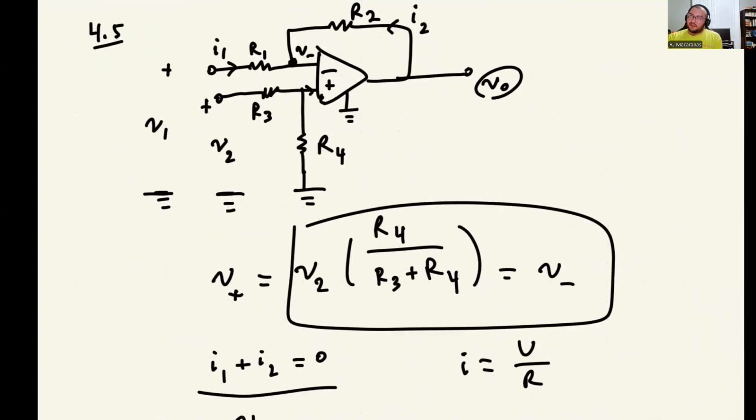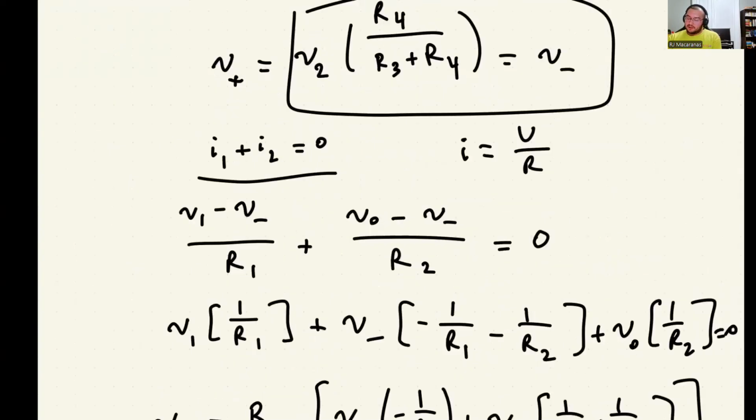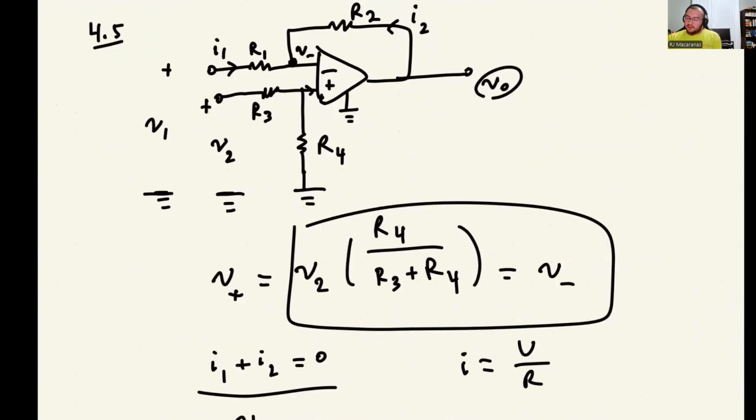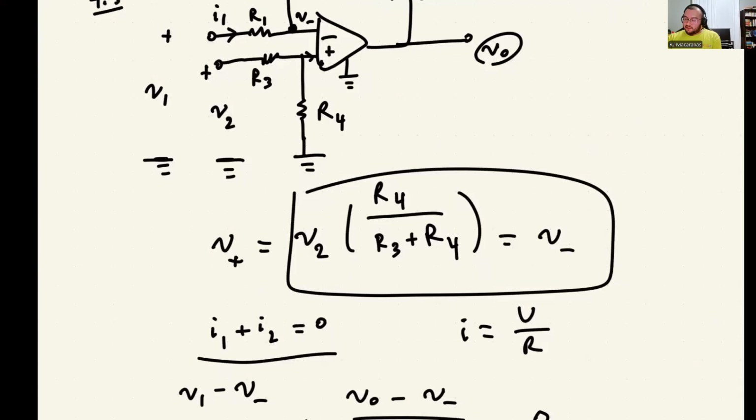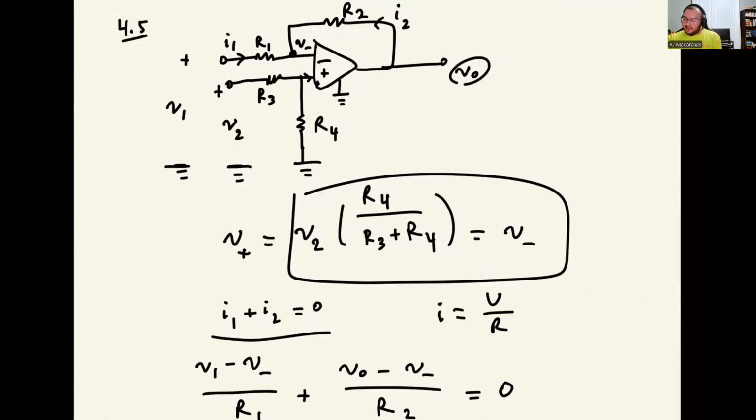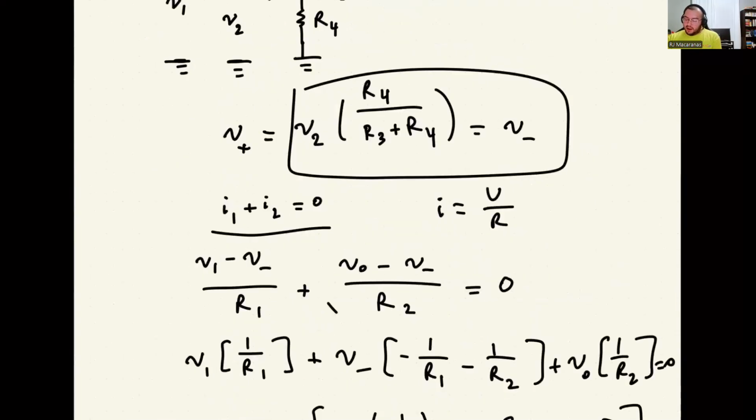And then the resistance that is occurring between those two potentials is R1. And so that's I1. And the same thing follows for I2. I've got V out, VO here, and I'm going from VO to V minus through R2. So that's where my I2 comes from. Good? Yes. Okay, cool.